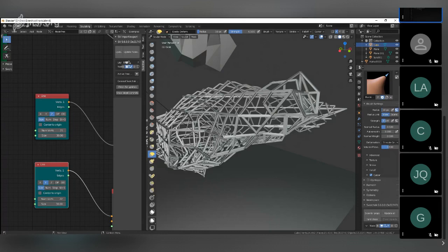Okay. There's a DXF page on the wiki, so if you've got a cool looking file that shows what DXF can be used for, because people have this idea that DXF is the poor cousin of DWG. Well, with the latest version of AutoCAD, if you save any model as DXF and then load it, it round trips perfectly. But a lot of that data is in a binary blob that nobody knows how to read. Okay, so that's cheating. But if you've got a good looking DXF that is only DXF data, a cool picture that people can download and play with, I think that'd be great to show people.